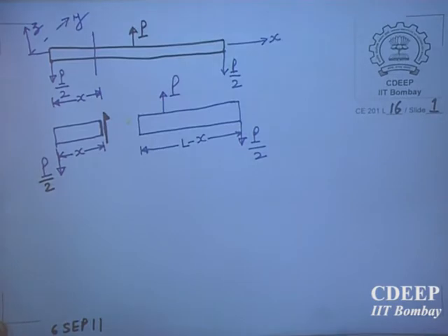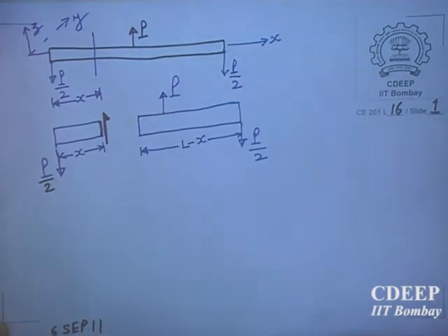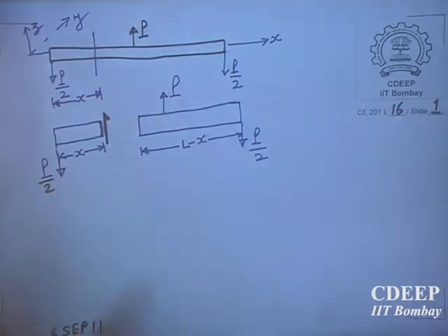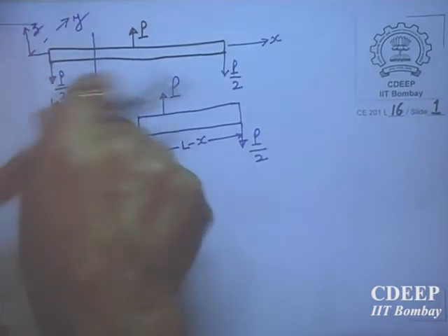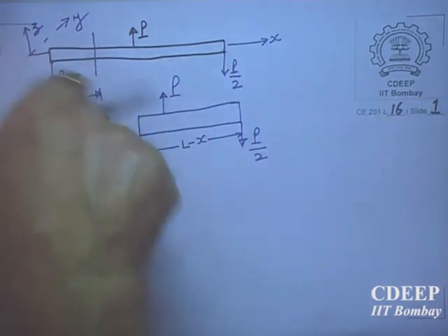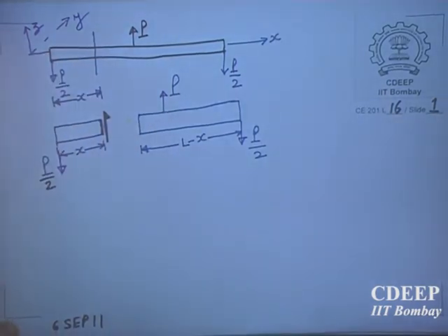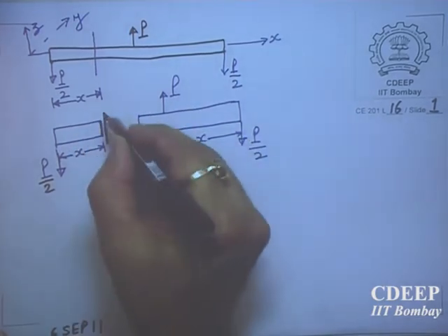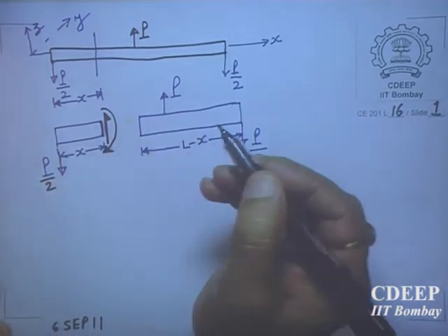You will say, no, why should it not be there? I am taking a general case. Vertical going in the Z direction, positive in the Z direction. Actually, it will be downwards, but then I am taking it in the upward direction. Now this one, if it is there, will cause a rotation of the entire element. Now, in order to balance that, about this point, there must also be a moment existing at this. So, in a planar beam, at least this one will be there. This is the moment about the y-axis.